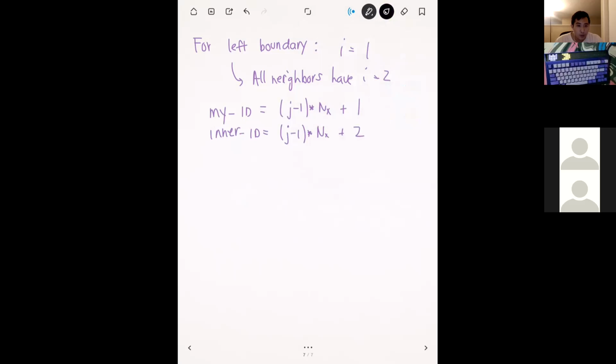All right. One more point I want to make before we jump into the example and the starter code is talking about the corner nodes, because it can be a little bit confusing what we actually apply on the corners here. The corners are the intersection between 2 different boundaries, and most of the time we're going to apply different boundary conditions on those 2 boundaries.